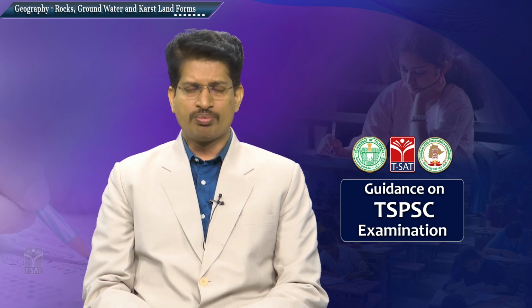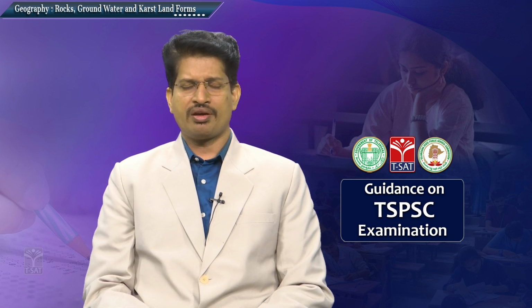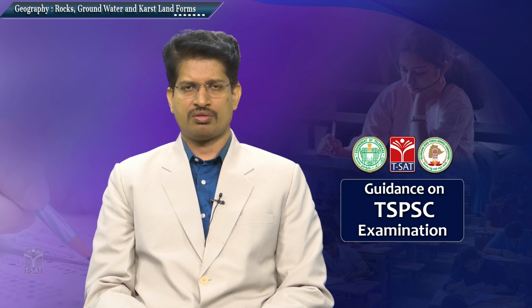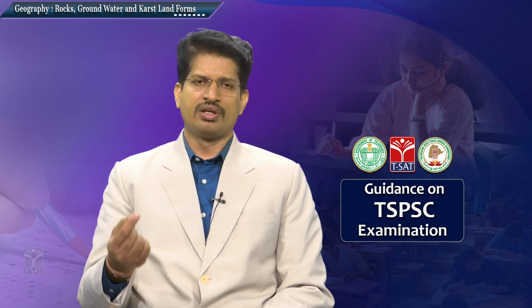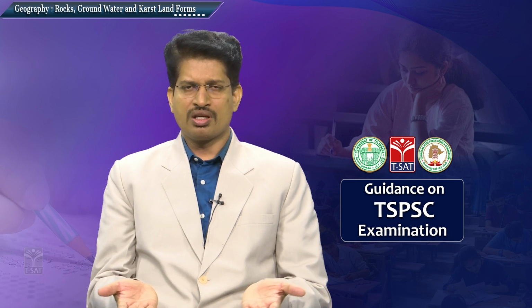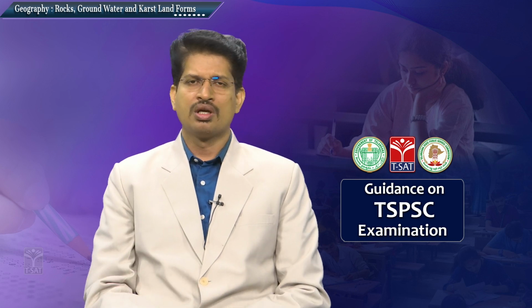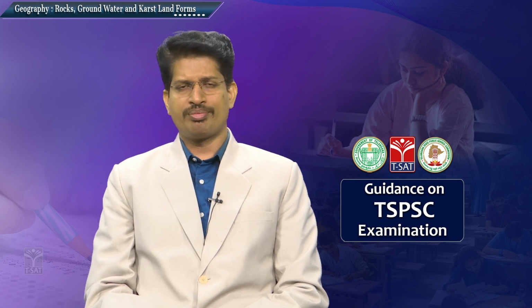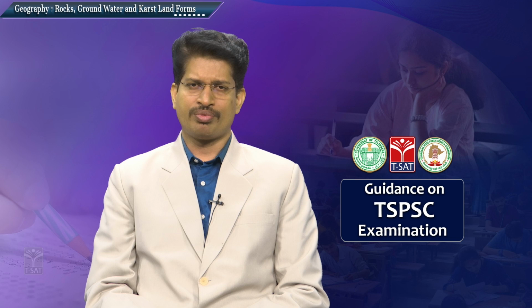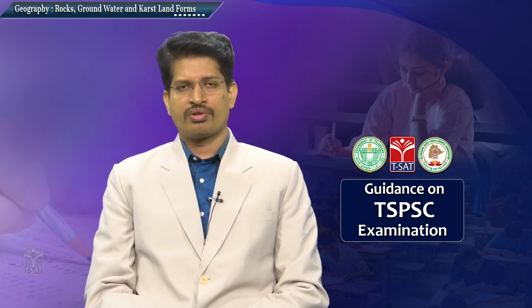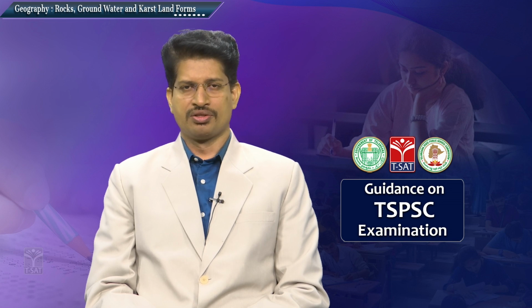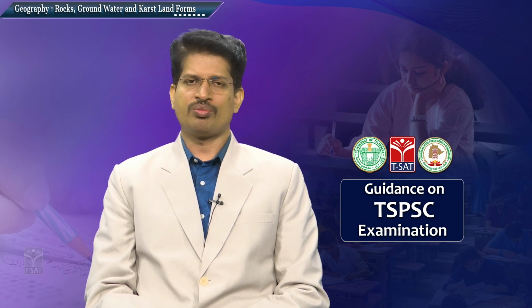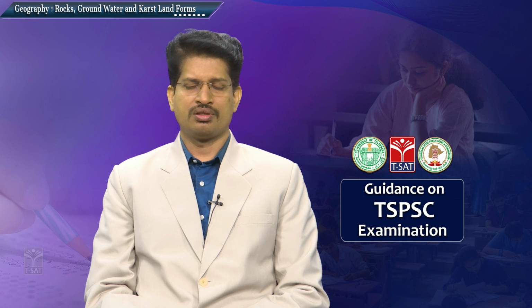Apart from this, the bottom rock must be impervious, meaning it must not have any pores, because if the bottom fundamental bedrock is porous, the water escapes down and the availability of water in the rock doesn't happen. So, another important fundamental factor apart from the porous and pervious nature is that the bottom bedrock must be impervious. These are the conditions essential for the formation of a water table.